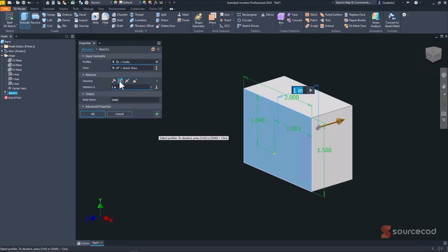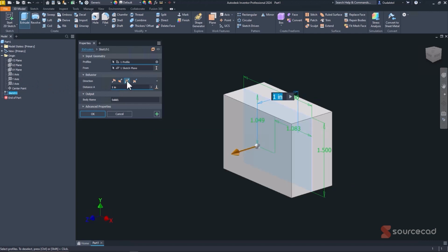If I want my work planes to be in the middle, which is something you really should consider, these work planes that are right here are very, very useful. Easily forgotten because they're inside a folder. But if I want it in the middle, that means my number, and you can kind of notice where this blue tinted, that's my sketch surface, and it goes equally both ways.